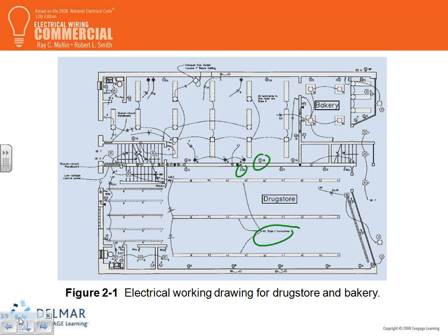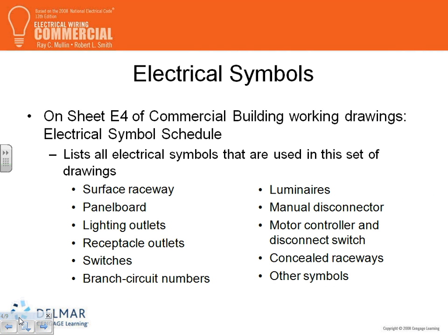If we're showing it in 2D on page 29, the upper right, guys, you can see the circuit is like a circle with a dot. Please be aware that if it's a dot, this means the conduit is going what? Up, going up. If it's a cross, the conduit is going down. That's something we need to know. The rest of them, I'm very confident that you guys know how to read these.